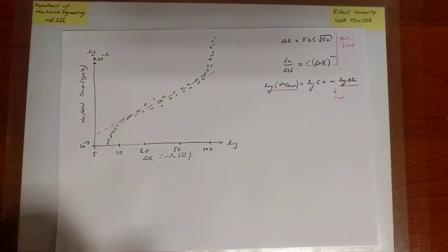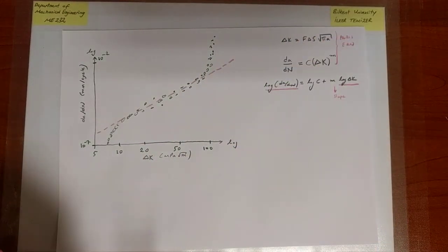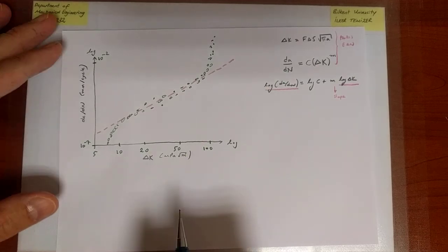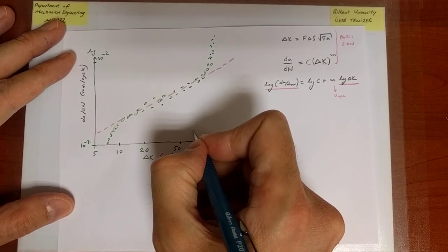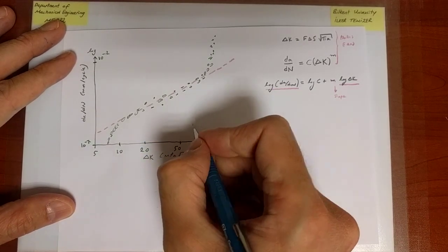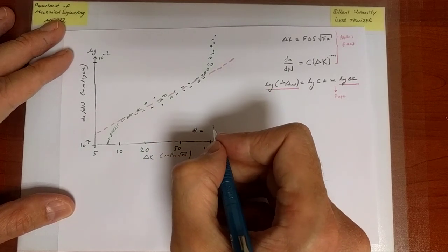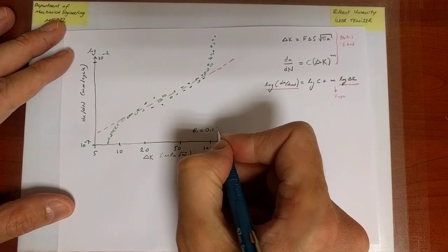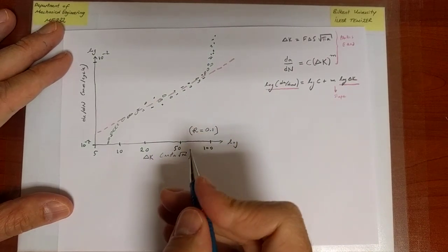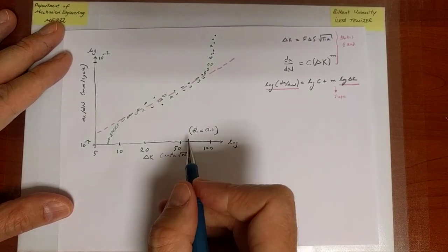Okay, so now what is it that we are observing? Incidentally, here I should also write that the value of the stress range, which ultimately goes into delta K, the intensity range, does matter, but so does the value of the stress ratio, the ratio of S min to S max. In this particular case, the ratio is 0.1. This is just to emphasize that eventually the value of R will also matter. So we're going to think about how to incorporate that.